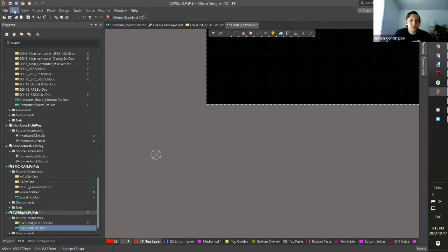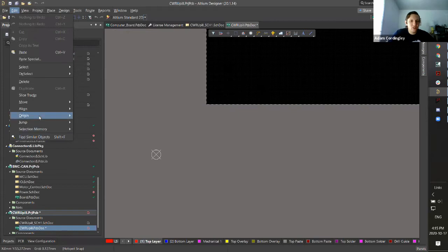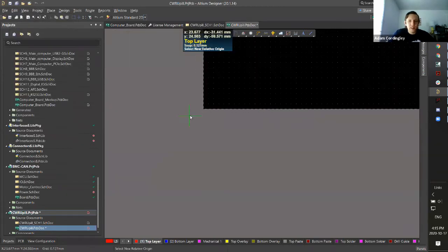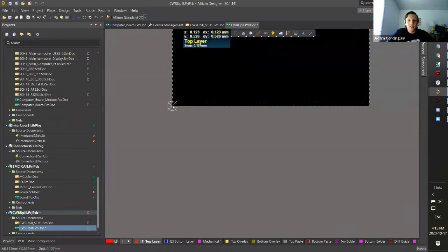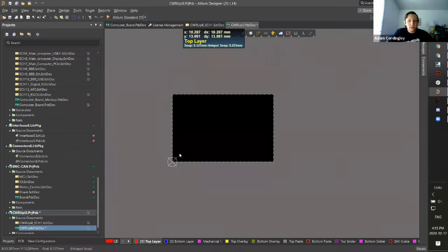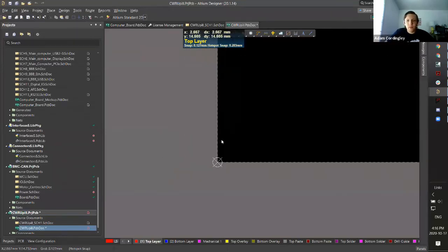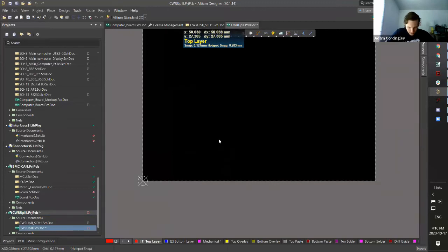Yeah, so I switch the origin. I go to Edit, Origin, Set. Then I zoom in to make sure I'm right there and set. Now the origin appears there. I could set it anywhere I like, but this makes sense because positive X is going to the right, positive Y is vertical. So now the origin is set right there. Great. From there, I think we're good.